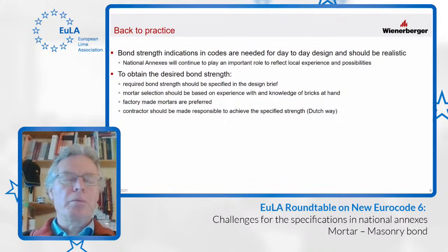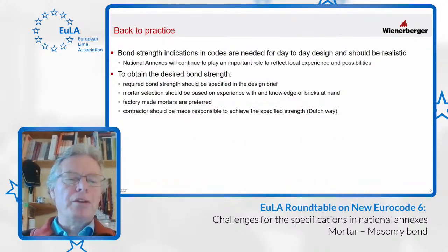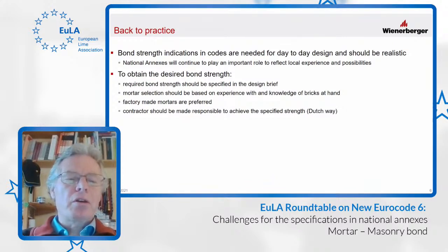And it's funny to say, that was not my intention, that he said that the Danish National Annex assumes a one-to-one relation between the initial shear strength and the fxk1. And I think Denmark and the Netherlands are on one line, because in the Dutch National Annex, that's also the case. I think that's one aspect, calculating with a bond strength, a flexural strength in design.